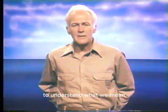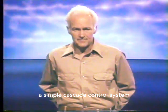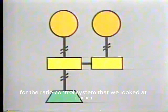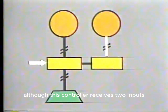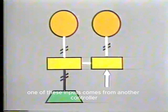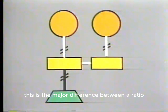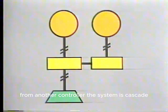To understand what we mean, let's look at a logic diagram that represents a simple cascade control system. This logic diagram is similar to the logic diagram for the ratio control system that we looked at earlier, but there is one important difference. Although this controller receives two inputs, just as the ratio controller did, one of these inputs comes from another controller. And this is the major difference between a ratio and a cascade arrangement. In most cases, when a controller receives an input from another controller, the system is cascade.